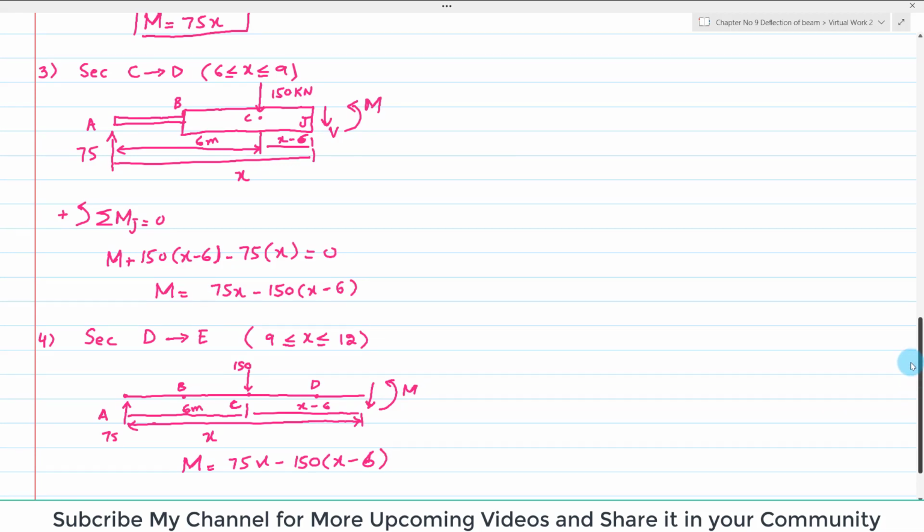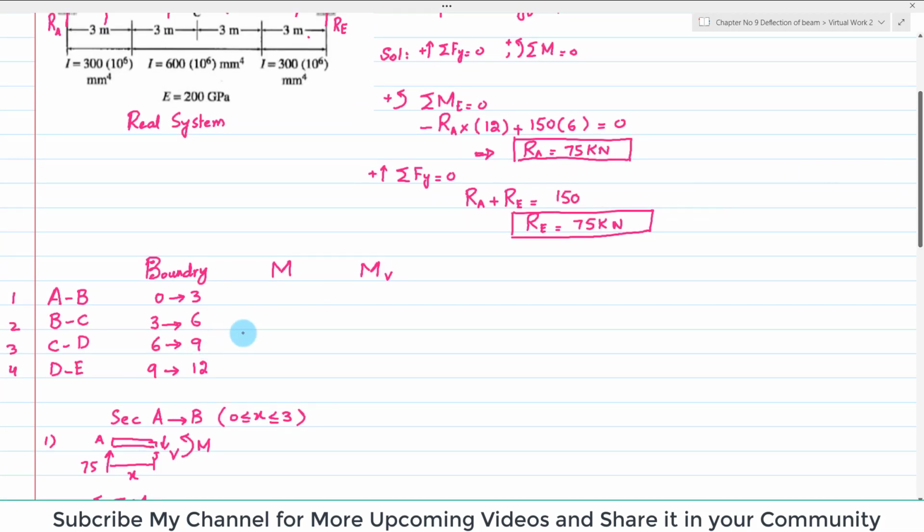I will write it. From portion A to B, you can again check it. The bending moment equation was 75x. From B to C, it was again 75x. From C to D, it was 75x minus 150 into (x minus 6). And from D to E, it is the same, 75x minus 150 into (x minus 6). Okay.